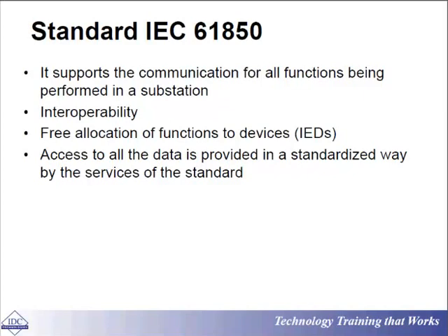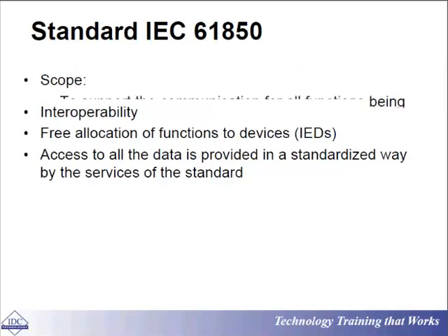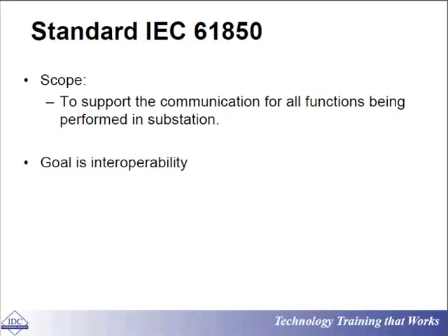It depends what kind of signal is to be transferred. Is that a protection signal? A control signal? An image signal? A voice signal? That function could be different, but whatever it is, it is part of that communication system. So that is the scope: to support the communication for all the functions being performed in a substation. If someone asks what is IEC 61850, that's it. This is the standard that supports the communication for all the functions being performed in a substation.